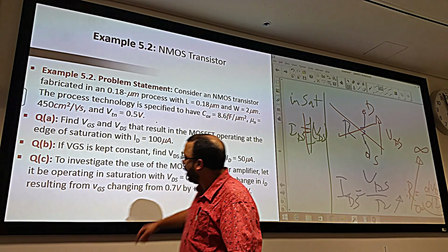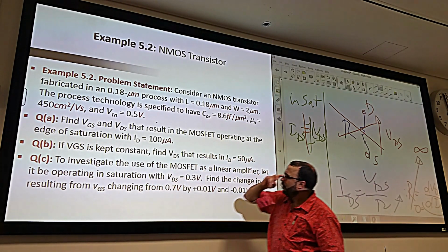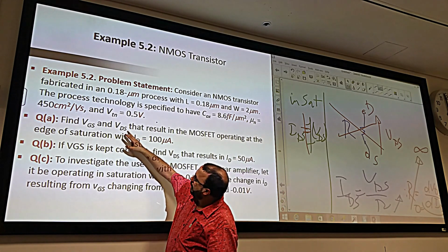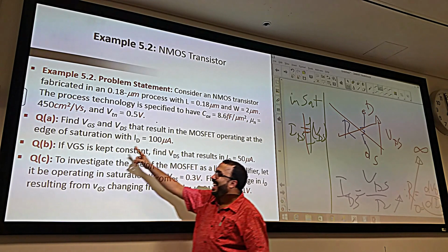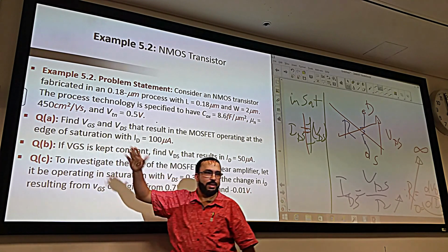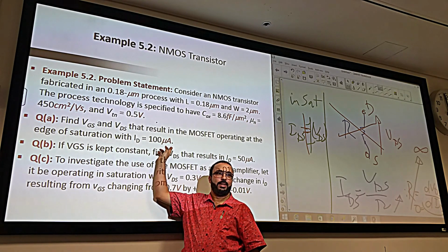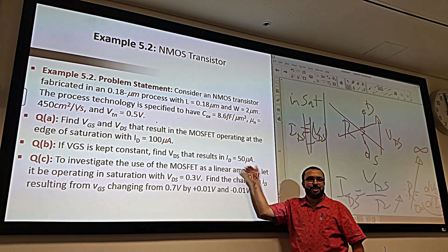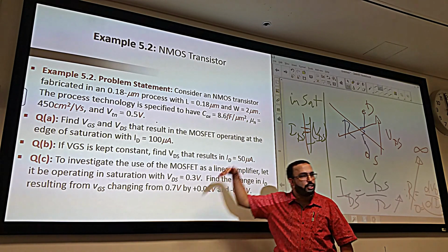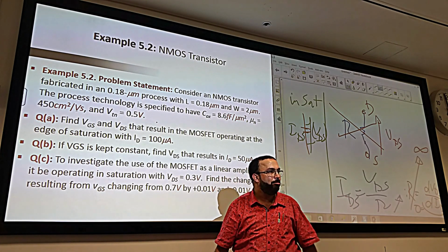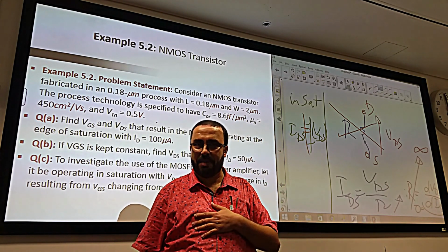And that's the way. Look here, it's very easy. What she said makes sense also, but this is also very trivial. Look here. In the question here, the MOSFET is operating at the edge of saturation. At the edge. At 100 microamp, yes or no? And then here where? It's going down, yes or no? If it is at the edge and is going down, it must be automatically where? Automatically in triode. This is how smart she is.